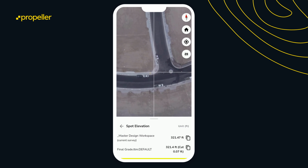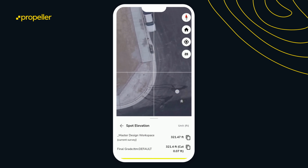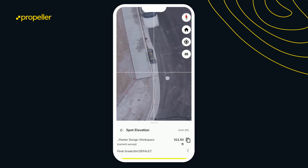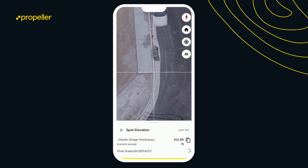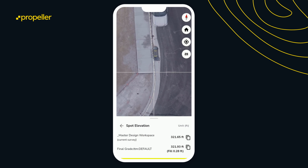So I'm just going to zoom in on this sidewalk here, this edge of curb. And what we can do is place that crosshair right over that specific spot. We're going to see the specific elevation for this model, so 321.65, and then the final grade elevation for that design, 321.093, and it's showing us we have a fill of about 0.28 feet.